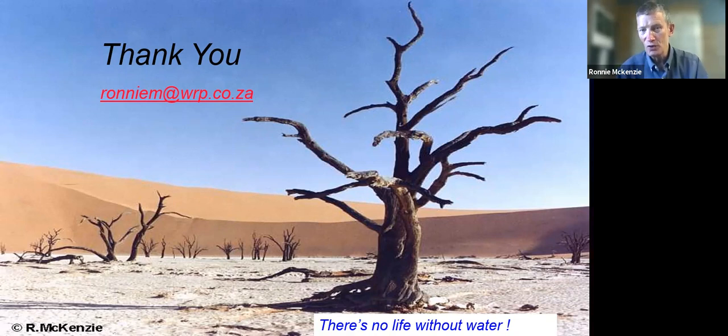And if you don't keep on top of that, then putting in a fancy controller is not going to help you. So our biggest problem is people messing about, excuse the French, with the boundary valves, and it changes the pressure profile in your zone, and there's no rhyme or reason to that. So it has to be a really smart controller to figure that one out.